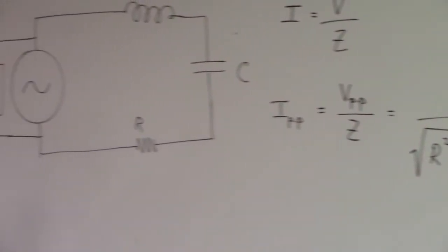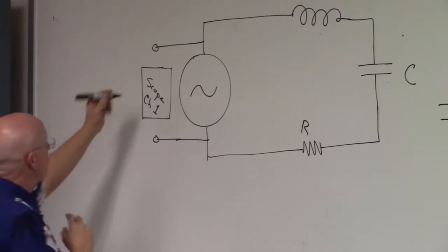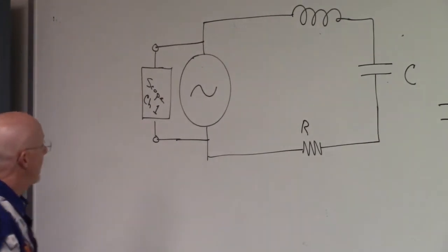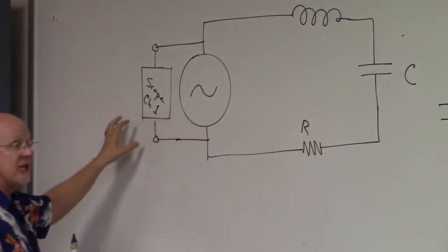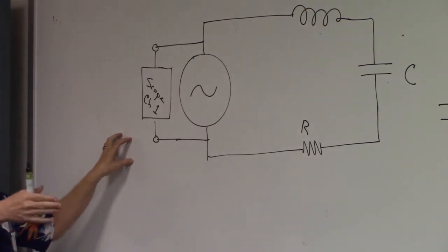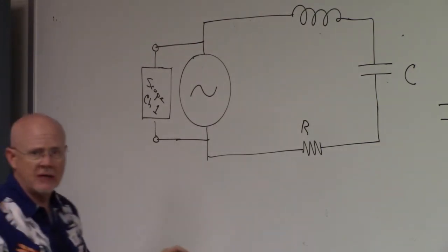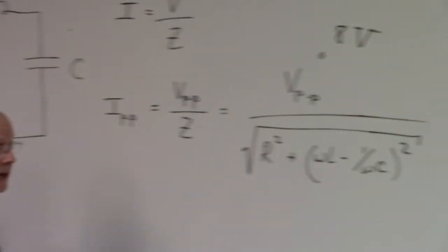So there's nothing really to write down other than just to remember that I'm going to put my scope on channel 1. Our channel 1 is going to be hooked to the function generator, and I'm going to just keep an eye on it. And with the newer oscilloscope, we will just turn on the button to measure peak-to-peak voltage and just make sure it always says 8 volts, okay?